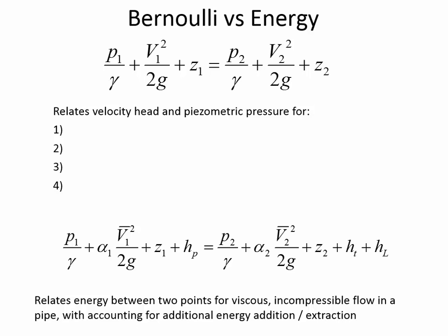And so in the case of the discharge from an orifice, we'd have location 2 be just as the jet has come out of the orifice, because there again we know the pressure, we know the elevation, and our only thing we don't know is the V2. So we're going to use that same kind of technique when we apply the energy equation. And so you can see that the pressure head term is the same, and so your thinking should be the same. Where can I choose as location 1 where I know a lot of things?